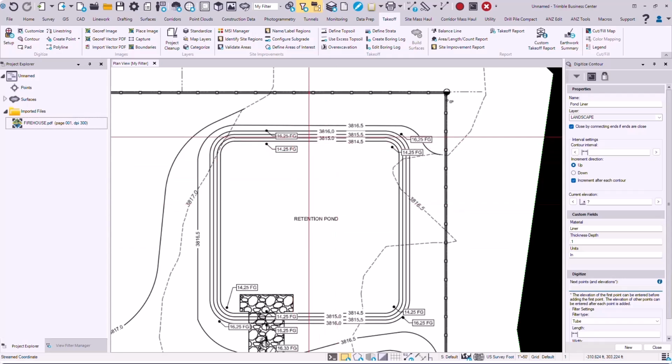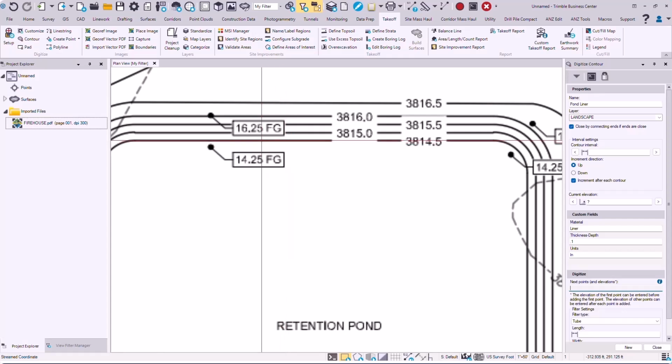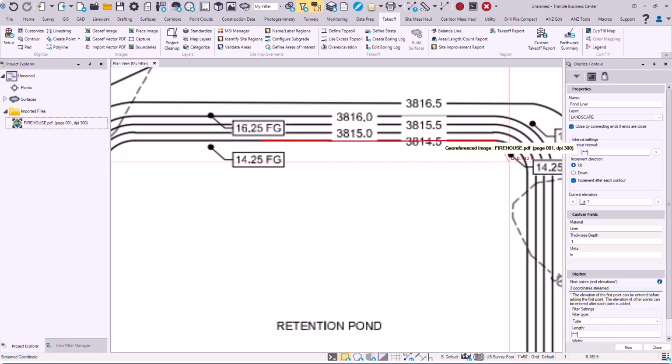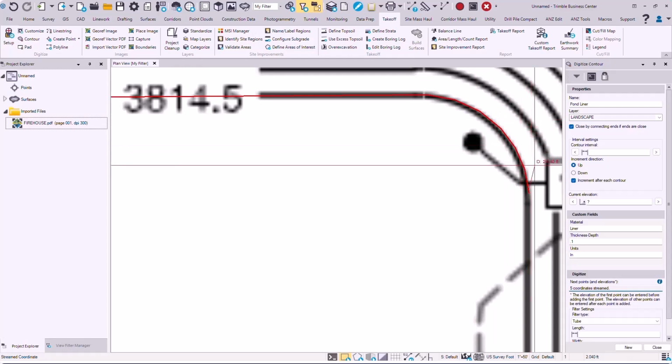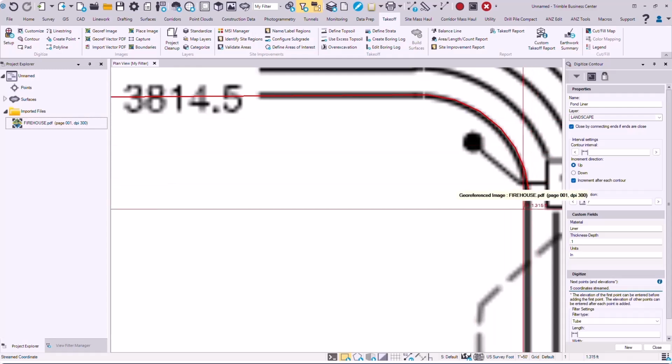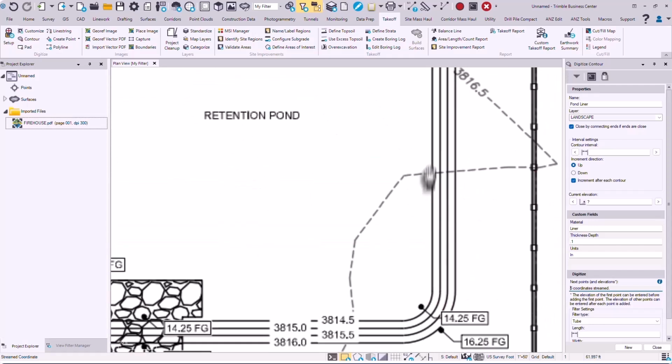In the past, digitizing contour was a click, click, click process. Here we'll click a starting area, click again, and so on and so forth. Well, now using the digitize contour tools, besides clicking a line in, if I hit the A for arc, that transfers this so I can click a point and a secondary point, and it turns it into an arc. We'll go back to the S for straight. Again, A for arc, S for straight.